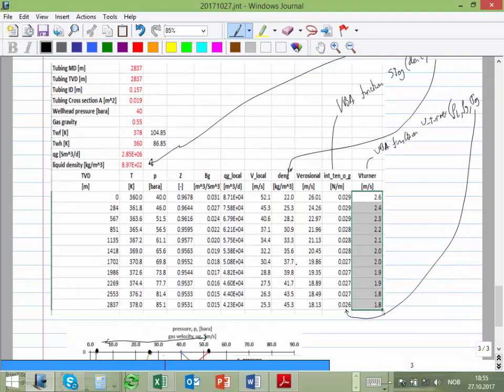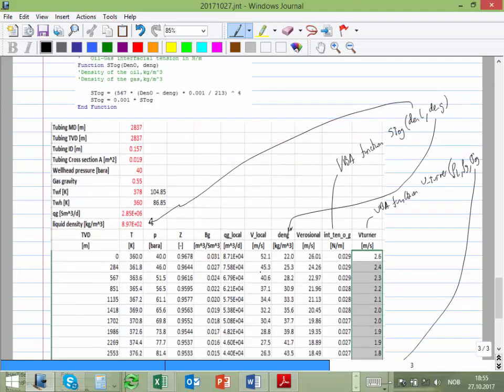No, well, it's a big job to change the pipe, and also it's going to give you less production. I think this is like a 6-inch pipe. That's a very, very big pipe. So another option that you might do is to increase the pressure. If you increase the pressure, this size of tubing is usually used for subsea wells, for subsea systems where each well has to produce a lot. And these systems don't produce with a wellhead pressure of 40 bar. They produce at a much higher pressure. And if the pressure is higher, then the rate is lower, and if the rate is lower, the velocity is lower. So probably you won't be violating.